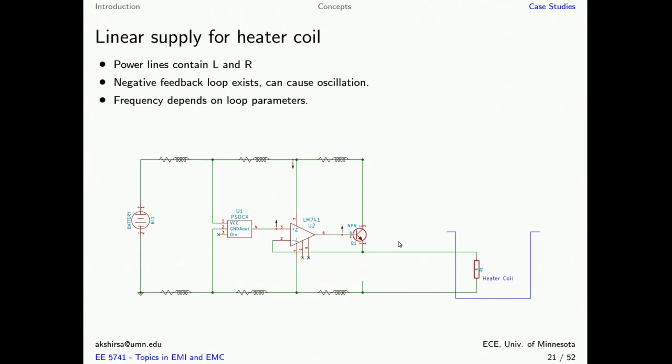This basically is a parasitic oscillator that has formed, and this can cause severe oscillation in the output depending on the circuit parameters. This is a known problem in many audio amplifiers. Under certain conditions, it could cause the output to start making a loud noise, much like a motorboat, and it used to be called motorboating. So let's see what is the solution to this.